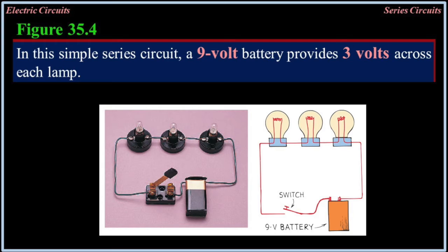the total resistance of the circuit. This is Ohm's law. 4. Ohm's law also applies separately to each device. The voltage drop, or potential difference, across each device depends directly on its resistance. This follows from the fact that more energy is used to move a unit of charge through a large resistance than through a small resistance.